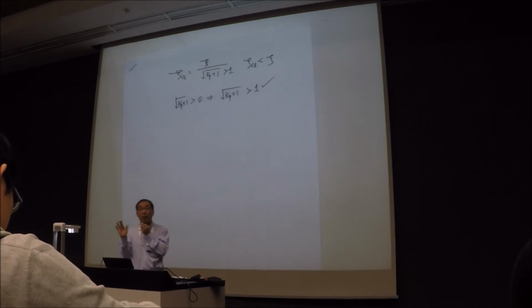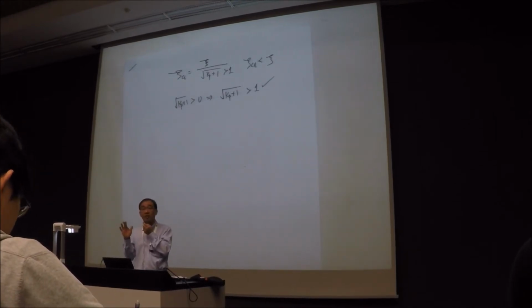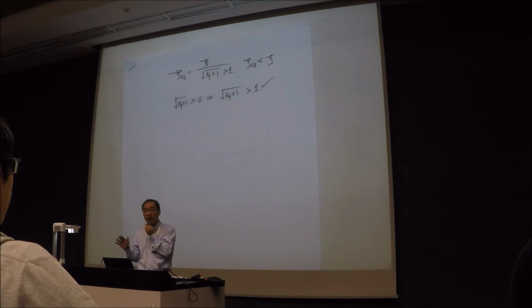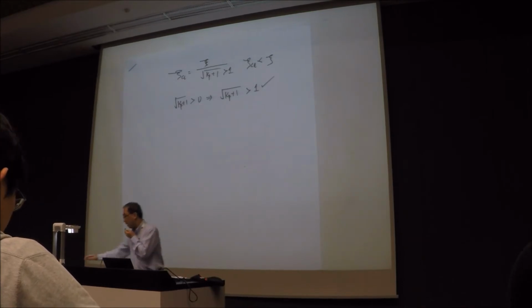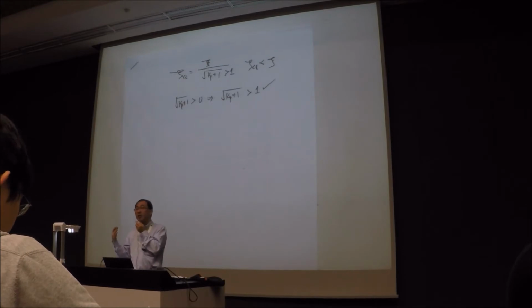Okay? And that is why you will see that if I have to close the loop using just a P controller, it is actually not very good because I'm just using a P controller. What happens now is my closed loop system will have a damping that is actually smaller than my open loop system.